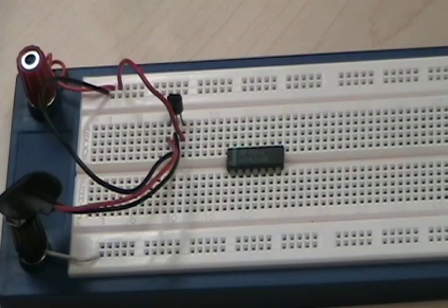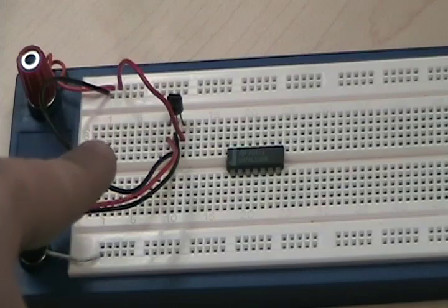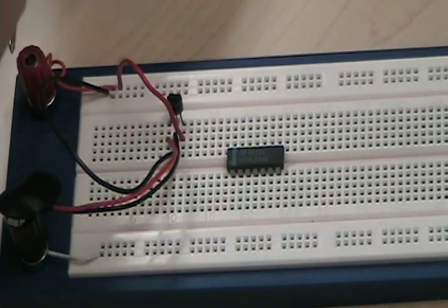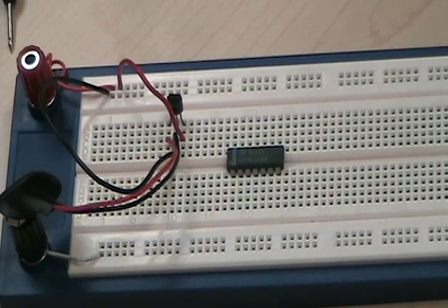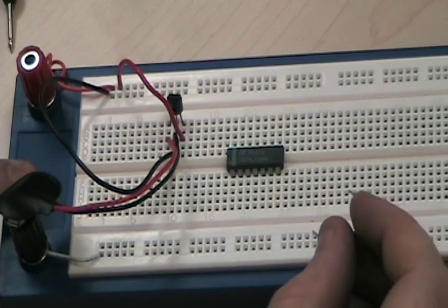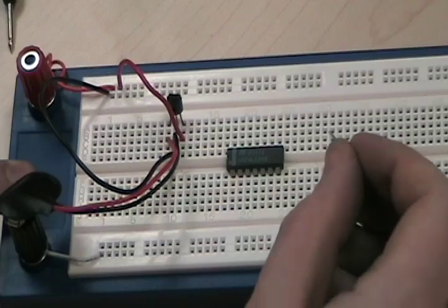I've got my power supply chip, my 78L05, hooked up. I hope you were watching this in order, guys, because I showed you how to hook up a 78L05 5-volt regulator. Remember, if you hook up more than 5 volts to this chip, you can very easily damage it. So first, we're not going to power up our battery, but we're going to ground our chip.